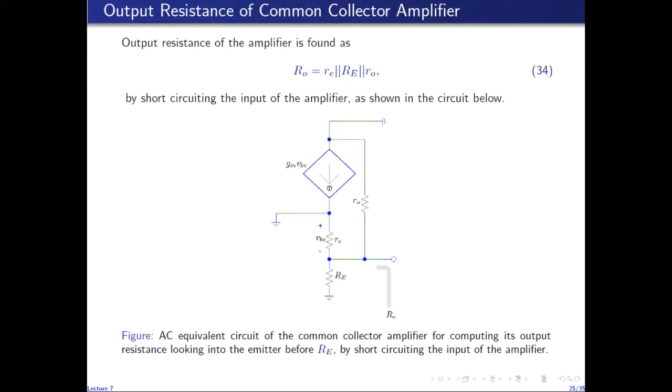So this voltage controlled current source is grounded on both sides. So there is a short circuit across this current source. You can think of this node as connected here, because these two are the same nodes. They're connected to the ground of the circuit. So this short circuit short circuits this current source, so you can ignore it. So we have a short circuit here,